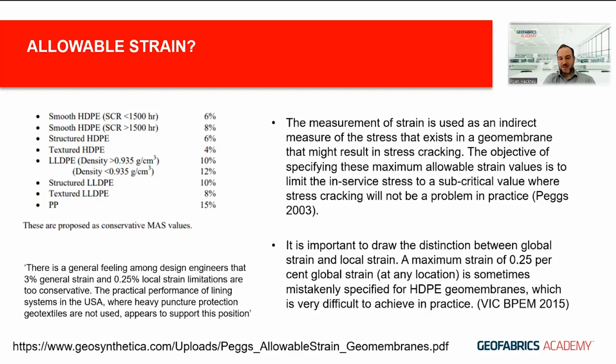You've seen that example that I gave you earlier of the LFA2 measurement methodology, where we're measuring those mean local strains, whereas in the ASTM methodology, we're actually measuring the maximum strain on that full plate. So that's assessing every single data point and measuring the strain across that full profile. And the end result is the maximum strain on that full profile that we've measured.